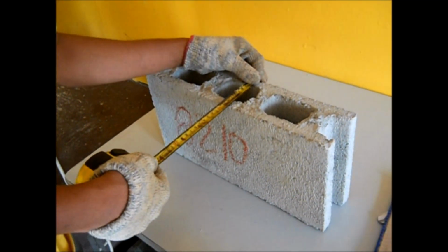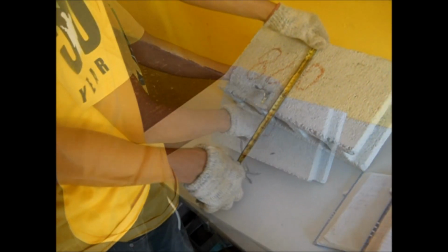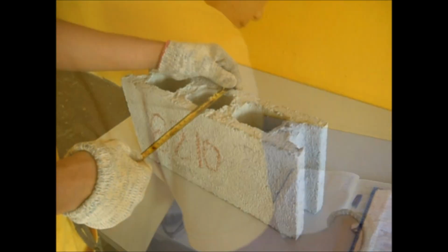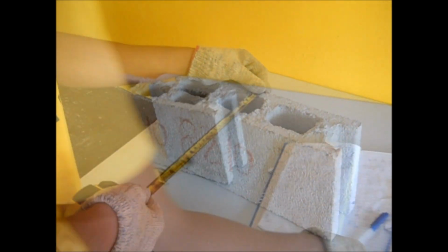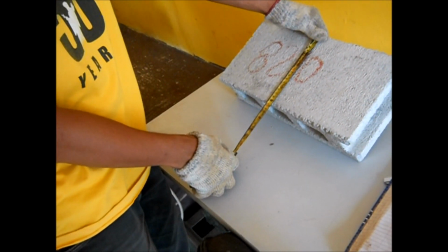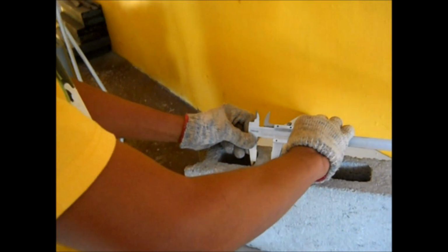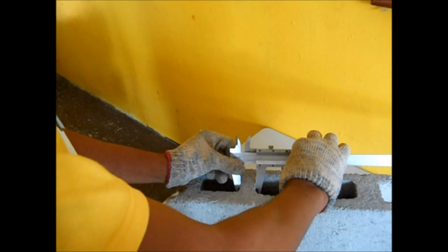Before starting the initial compressive test for the concrete hollow blocks sample, it is really necessary to measure the physical attributes like the length, width, thickness, and structural components of the sample. Proper and accurate recording of data should also be observed in the laboratory. For near-to-exactness measurements, a lab caliper is highly advisable to measure the web and face thickness of the hollow block